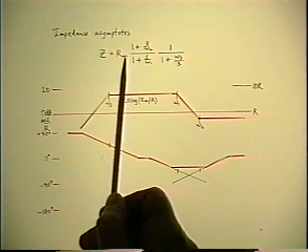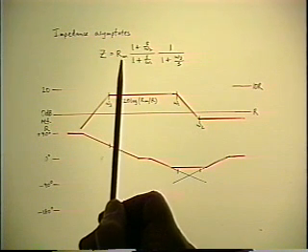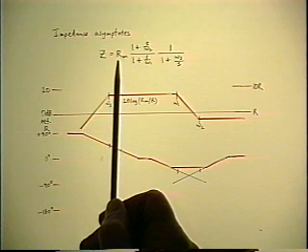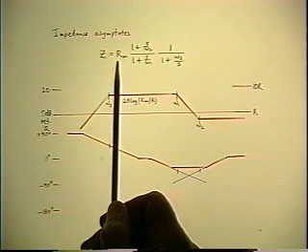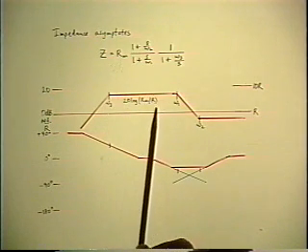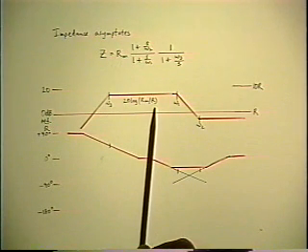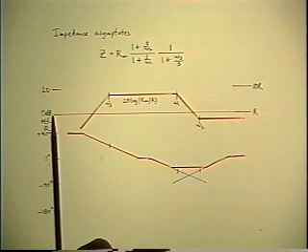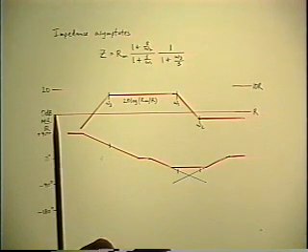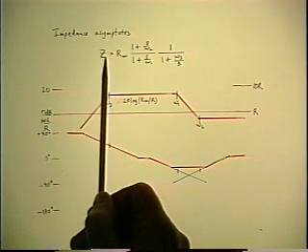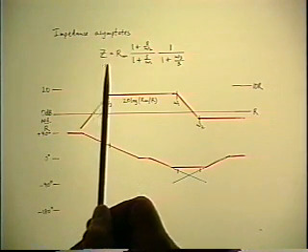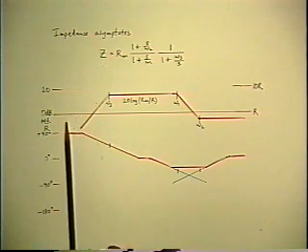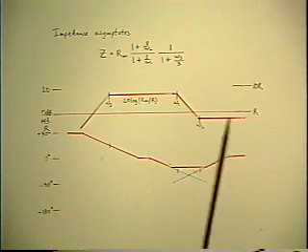And that makes this coefficient dimensionless again, just like a voltage gain. Then you can convert it to dB by taking the log and multiplying the log by 20. So the reference resistance that you have chosen then corresponds to the 0 dB level, because 0 dB means a ratio of 1. So when you have 0 dB for the magnitude of the impedance, what you're really saying is the magnitude of the impedance is equal to the reference resistance when the ratio is 0 dB.